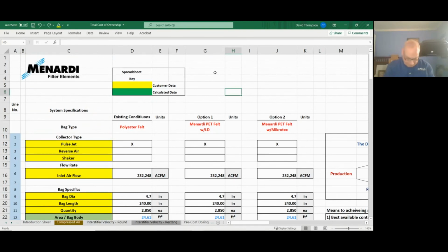Okay, thanks, Dave. So another question from Sean is, how do you remedy a situation where your upward airflow is higher than it should be? Well, as I mentioned, there's not that much you can do about that. Typically what some people do is compromise between losing a little bit of filter area and pulling some bags out, giving more area between the bags so that the material has more of a chance to drop off.